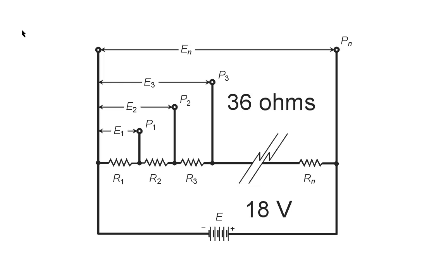Well, you can go back to the choices here and look at the B and C. If you add all those values up, you're not going to get 36 ohms, so you can rule B and C out right away. You can go to choice D, 4 resistances at 9.0 ohms. Well, okay, that looks pretty good. 9.0 ohms, 4 of them, 36 ohms. And it draws 500 milliamps.